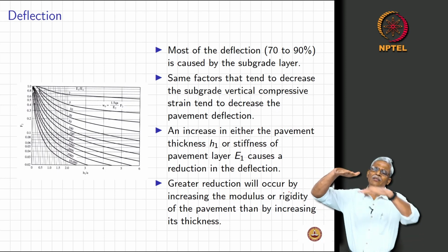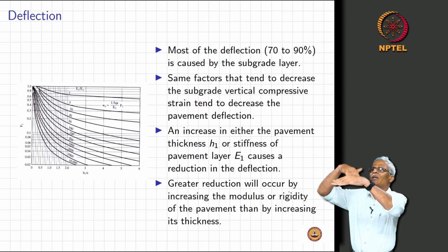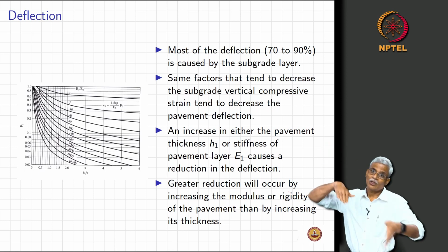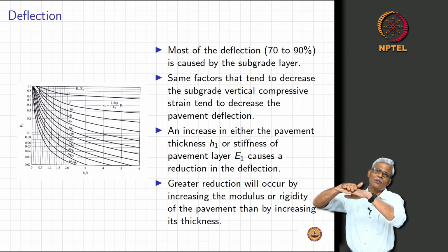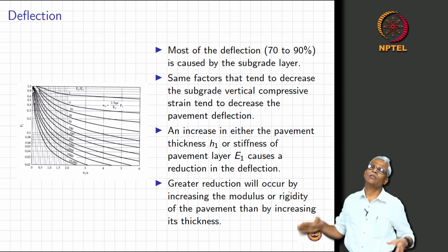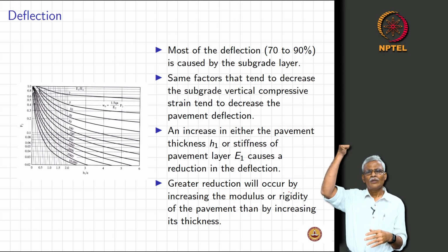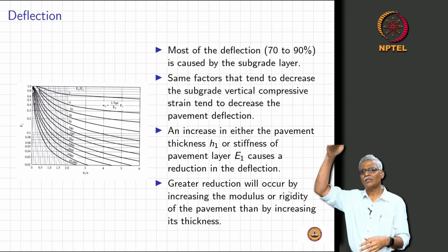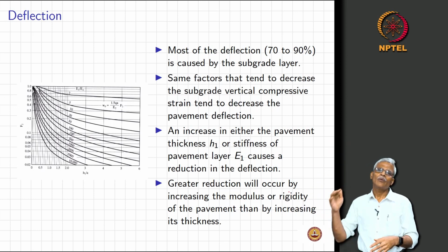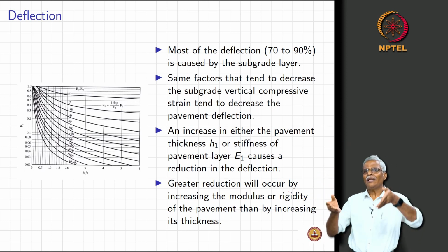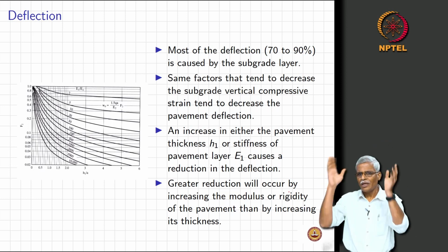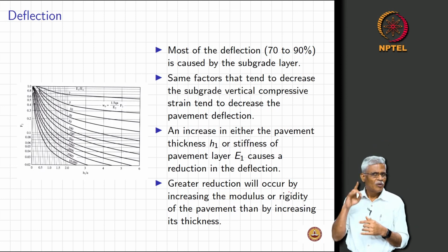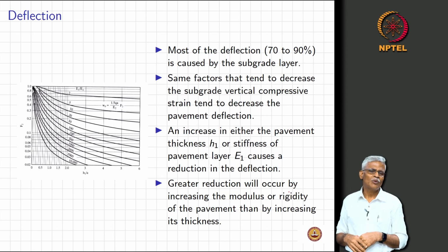This is like stacking one layer on top of another, because we assumed the interface is continuously in contact, with no slippage happening. So when a failure happens in one of the layers, let us say the third or fourth layer from the top, what will happen to the other 3 layers on the top? They all will also fail. The failure will be seen by you only on the surface.